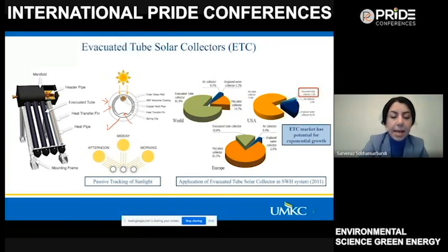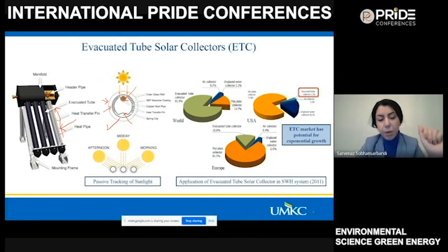transfer this heat. And then within the collector, we have a copper heat pipe, whose responsibility is to transfer the heat absorbed through the collector, and pass this absorbed heat, through the evaporation of a small droplet of water or glycol, to the water passing through this manifold. Basically, it's converting the sun radiation to heat, which is passed through this manifold, but later on, we just absorb it and store it in your tank.